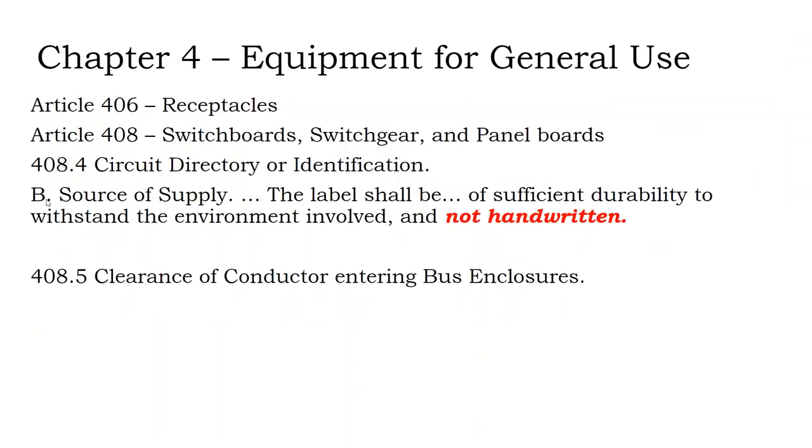So here's an interesting one. It says for switchboards, panel boards, and switchgear, the directory should not be handwritten. We'll see this in labeling requirements, locating disconnects, and putting inverter voltages and amperages. Back in the day, we would just have blank stickers and use a Sharpie to write the voltages and amperages on the label.